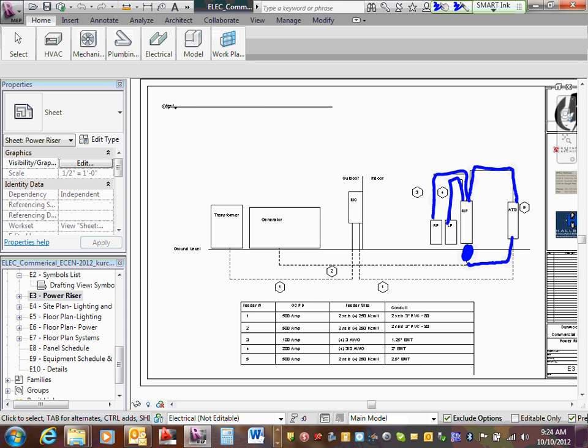So you have your transformer sitting right here. We have a generator you guys are going to size. That's a gen. Because we are higher than 400 amp, you have to have a termination box. We threw this one on the wall here. So you come out from the generator, from this one in, and from this one out. And then emergency panel is coming directly from here into the auto transfer switch. Can you guys see the picture, how the power is coming into the building?